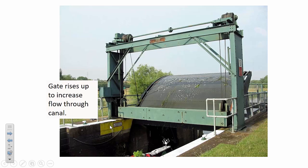In the case of a radial gate, you can't quite exactly see it, but the radial gate just rotates. I think I maybe have a side view in a minute. It rotates about a central point, and so with the water level, all of the forces are pushing in towards that central point, and it doesn't create any kind of a moment that's pinning the gate closed. But as the water level goes up, so does the flow rate through the gate.